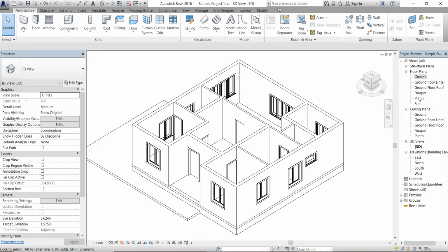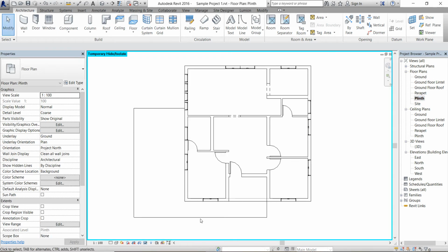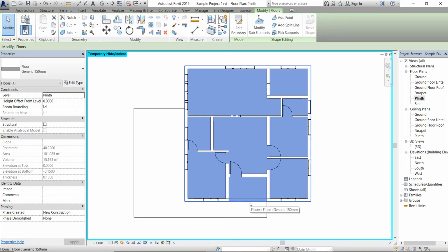first floor. We are going to use the copy tool to create the roof as the shape of both ground floor floor slab and ground floor roof is the same. In Revit, the copy and paste buttons are found in the Modify tab. We can select an element and then click the copy button to copy that element. Then if we click on the paste button, there are few options.